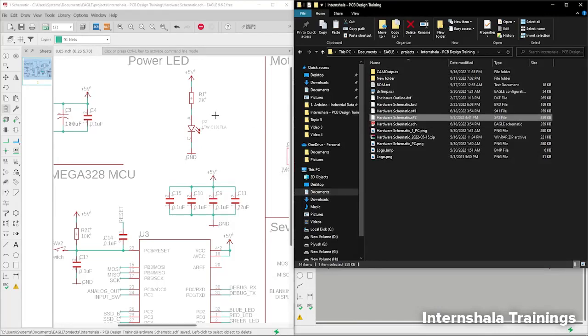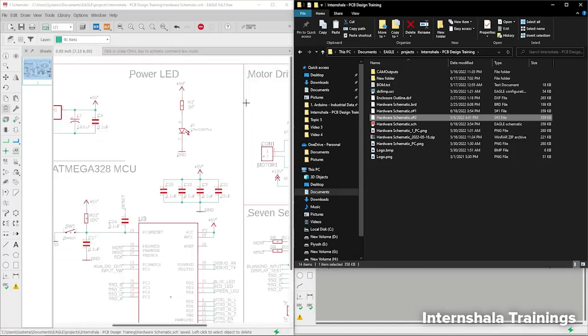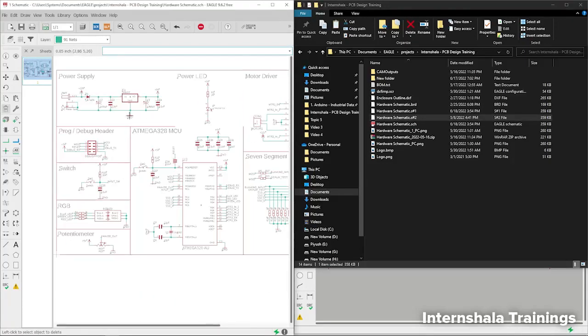Every time you press the save button, the software is going to create a backup of your project. And if you are not saving your work manually, then every 5 minutes the software is going to create a backup. Okay. So let me delete some more lines, and let's create a total of 9 backups.